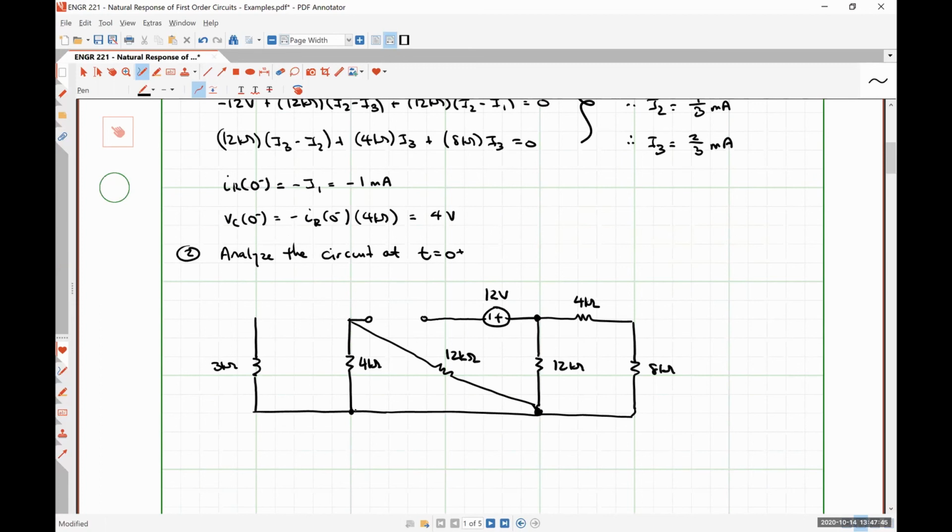All right, so the last thing that we need to discuss is what is going on with the capacitor, okay? I believe Davis covered with you guys on Monday the current and voltage relationships for capacitors. Part of those relationships is that the voltage drop across a capacitor cannot change abruptly, meaning that if the voltage drop over the capacitor at t equal to 0 minus is 4 volts, then the voltage drop over the capacitor at t equal to 0 plus has to also be 4 volts. Now, there is no regulation about the current flowing through a capacitor changing. It can do that as quickly as it needs to, and it can assume any value that it needs to.